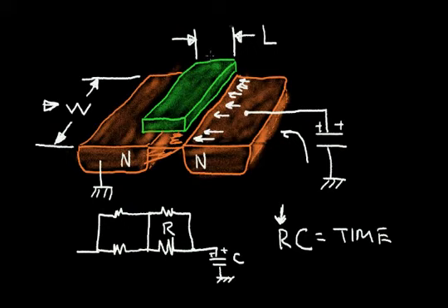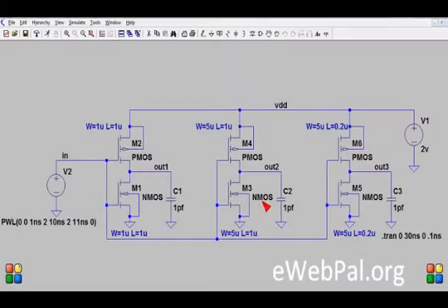So let's now review the schematic for the CMOS inverter. Here I'm in my schematic capture program, and notice that I've captured 3 different inverters. The first one is here, the second one is here, and the third one is over here. And notice that the output of each inverter is connected to a 1 picofarad capacitor. This voltage source here generates a 2 volts power supply that feeds across here to our P-channel transistors. And notice that the source of each N-channel transistor is connected to ground. And also notice that all of the inputs of the inverters are connected together over to this V2 voltage pulse.